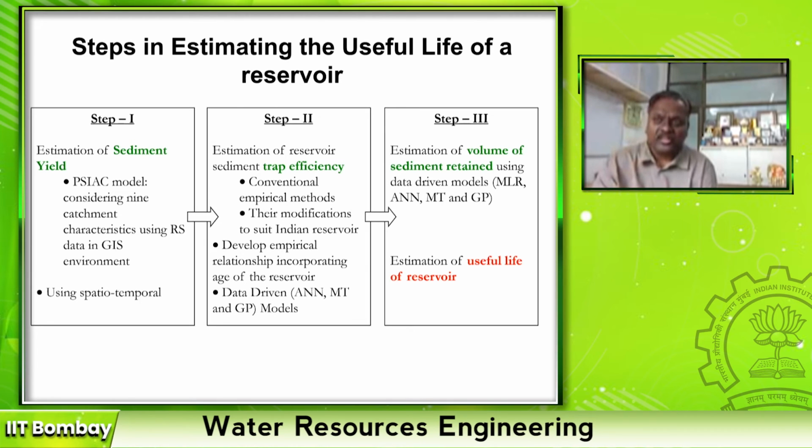They do the sounding depth in radial direction from the dam face throughout the dam. Then there will be a change in the contour level because of sediment deposited. That means you have to redraw the contour maps and the area elevation curve. The difference between the previous area elevation curve and the current area elevation curve will give you the reduction in volume of water stored because of sediments. From that also people used to estimate the trap efficiency.